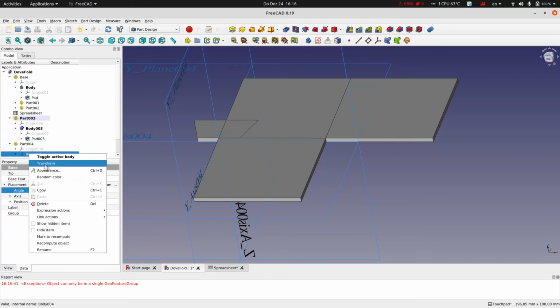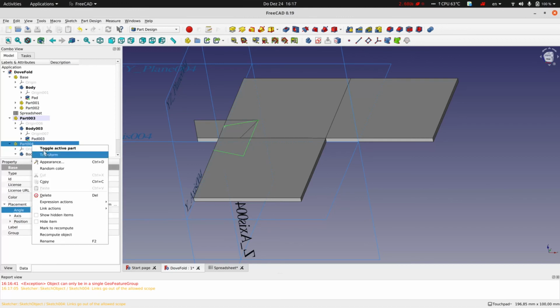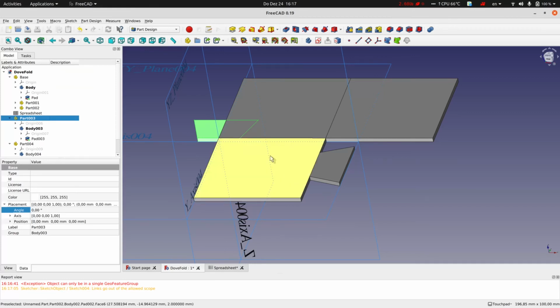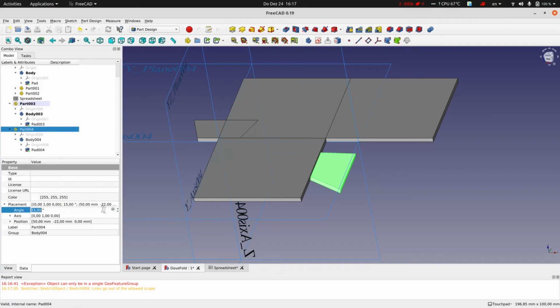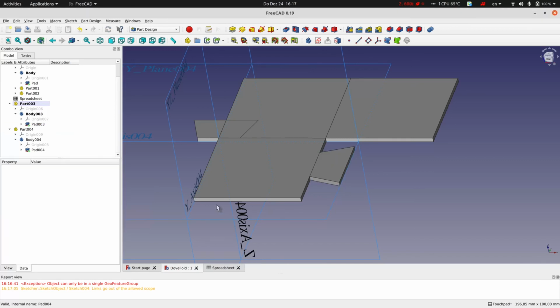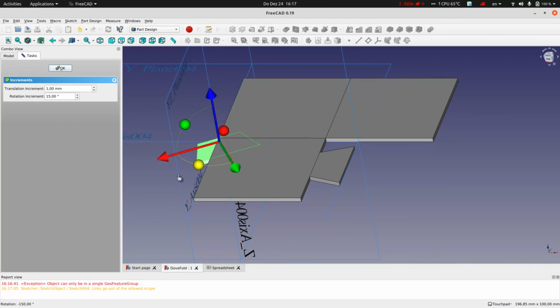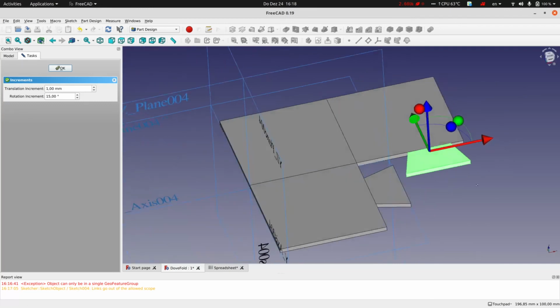move. First of all, we're going to rotate this because we want it along this edge. Okay, that's good. Now we're going to move the part, because that contains the axis along which we want to rotate, into position. So usually I'll do this with expressions. Okay, and then we're going to do the same old trick as before. This is actually part 4. We're going to rotate it in roughly the direction we want, and then we're going to add in our expression, which I should probably just copy paste, but it doesn't matter, it's not so much work. Hinge angle. Okay, and the same thing here for part 3. We're going to use the body to transform its orientation like that, and then we're going to use the part to position its origin system. So this is a lot like it works in Assembly 4 actually, except that Assembly 4 has some weird problems.